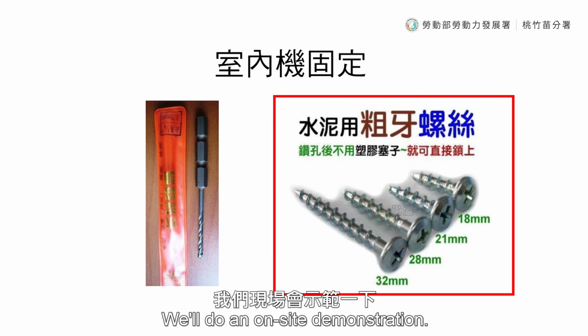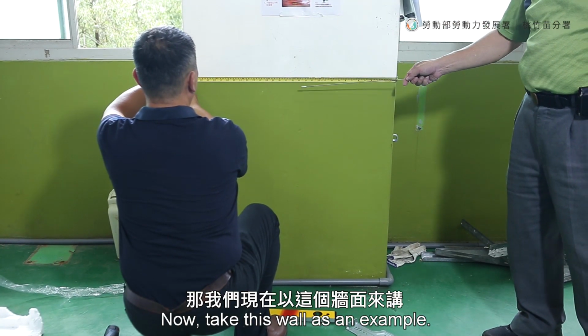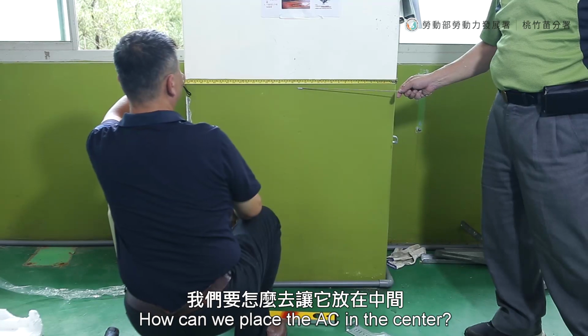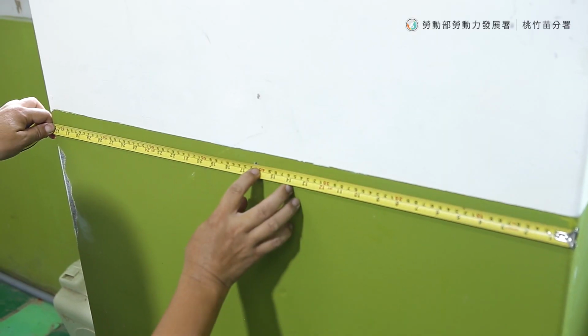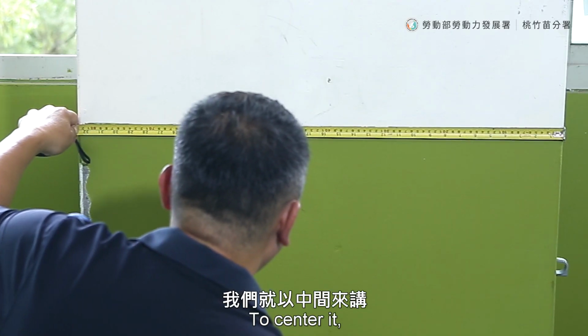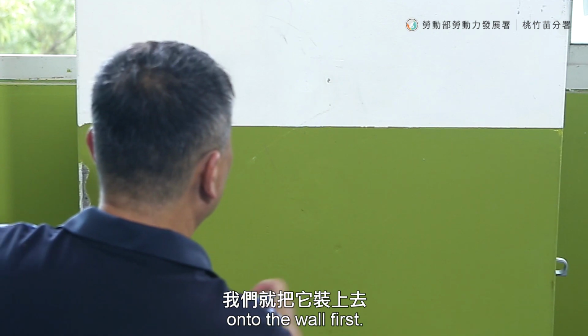We'll do an on-site demonstration. We need to measure its dimensions. Now take this wall as an example. How can we place an AC in the center? So we measure here is 82 centimeters. To center it, we'll attach the indoor unit's mounting bracket onto the wall first.